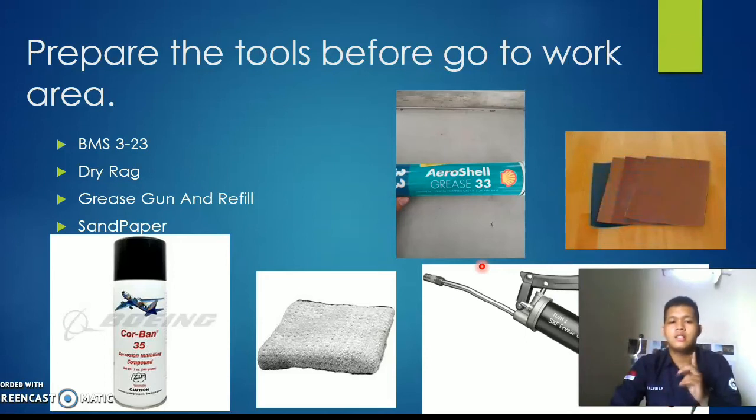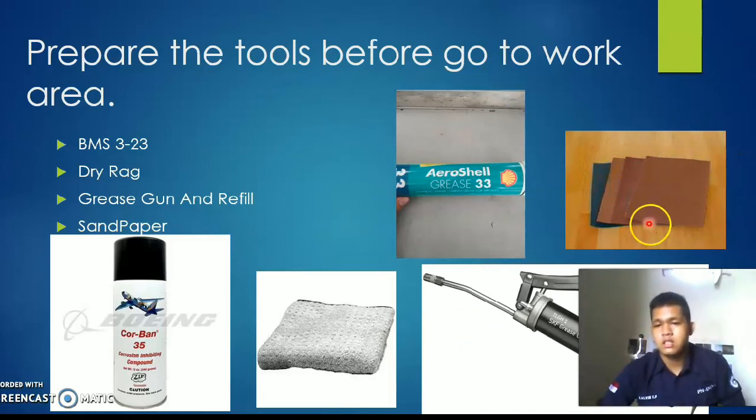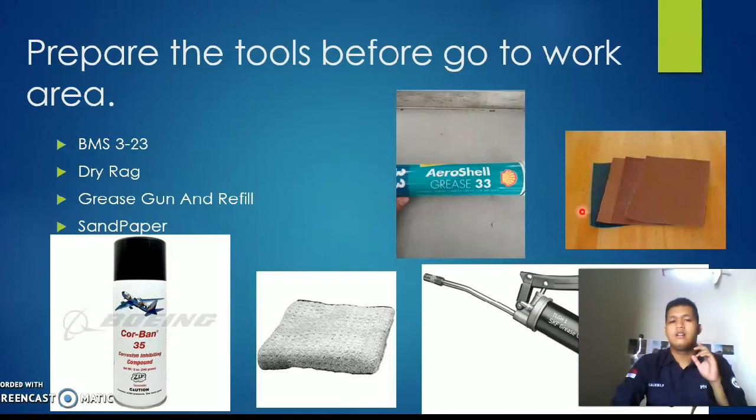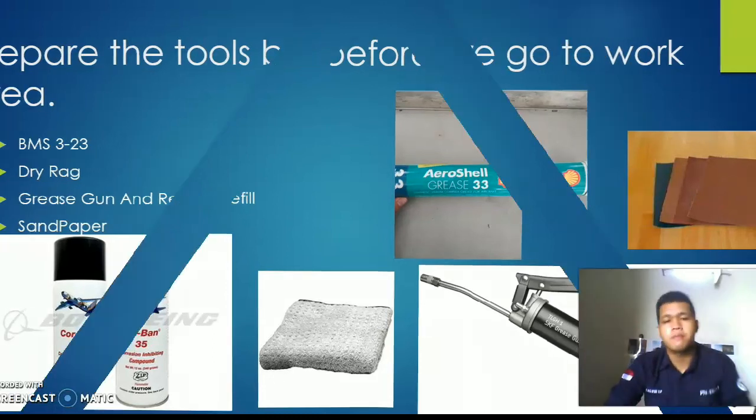And this is sandpaper. Sometimes we use this first red one, but sometimes we use the smoothest sandpaper. But remember, you cannot always use sandpaper, because some equipment, parts or components in the landing gear are more easily damaged if you use sandpaper. So be cautious when using sandpaper.